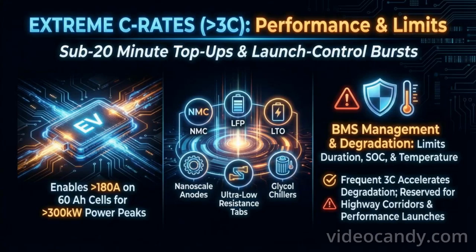Charging or discharging at 3C and above puts very high stress on the battery and requires excellent cooling. Frequent use can reduce battery life, so only high-performance EVs typically support these rates. In real-world EV use, extreme acceleration in performance vehicles may draw 3C to 5C discharge.